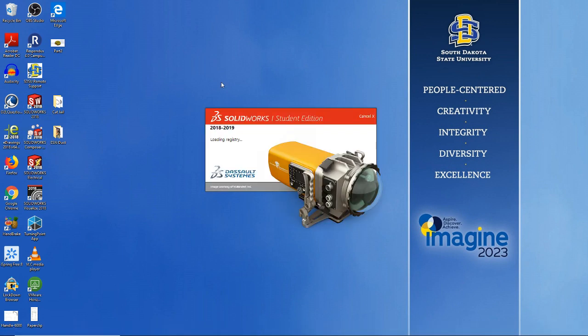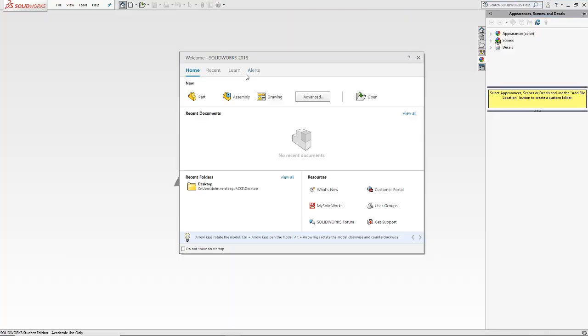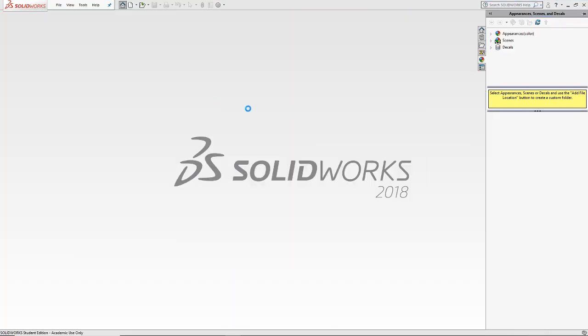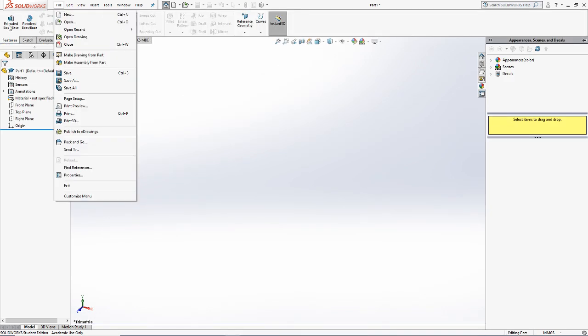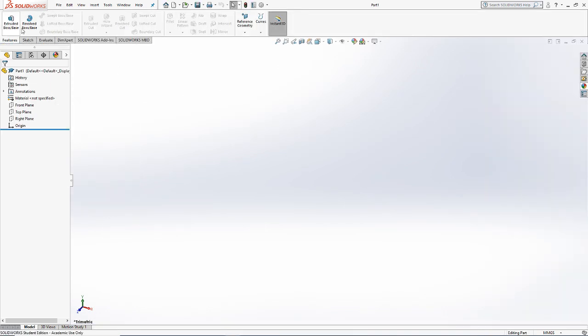If we open up SolidWorks, we're going to move past the first two features. We're going to move past the ones that are so big they take up the entire height of the ribbon. That's right, we're going into the features that are small. So between the first two extrusions here, that is the extruded base, the revolved base, up next is the swept base. Between the extruded base and the revolved base, you can cover about 70–80% of the material that you try to make. The swept base is specific but very useful under those specific circumstances.